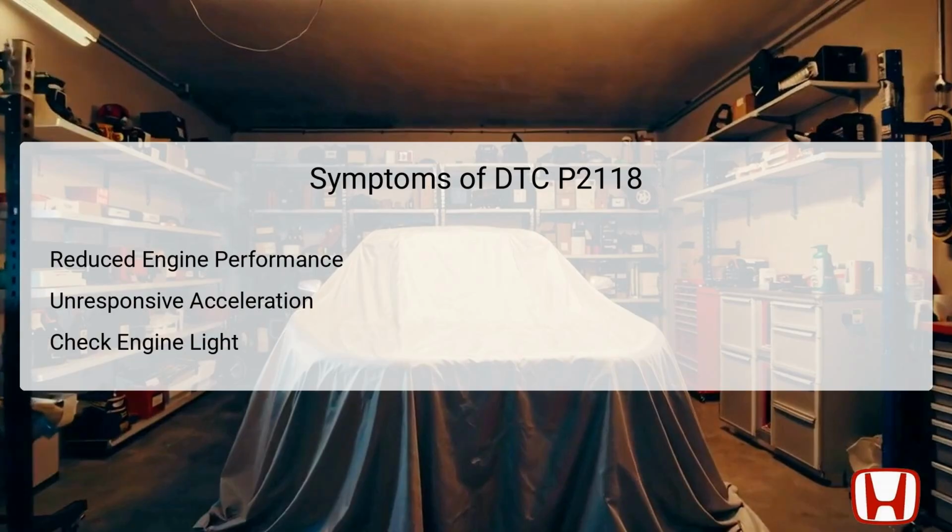An unresponsive accelerator pedal is another common symptom, where pressing the pedal does not result in the expected increase in speed, creating a frustrating and potentially unsafe situation. Additionally, the check engine light will likely illuminate on the dashboard, alerting drivers to a malfunction that requires immediate attention. The combination of these symptoms necessitates prompt investigation to avoid further complications.